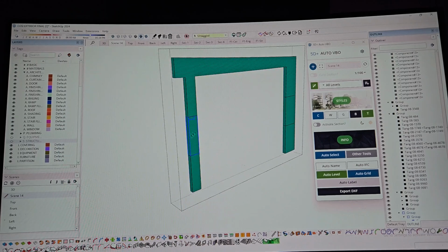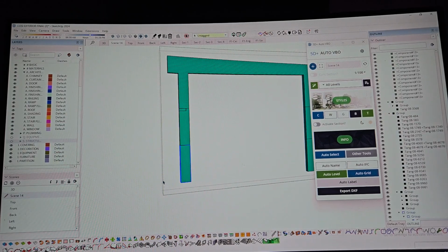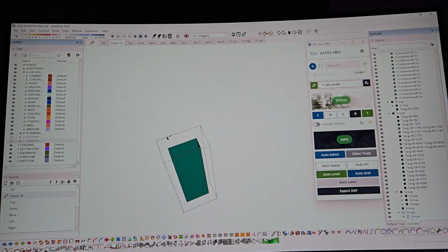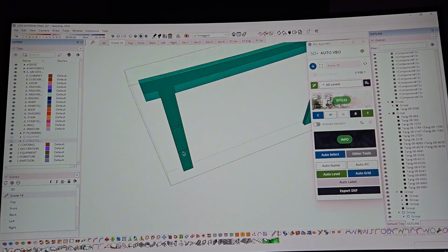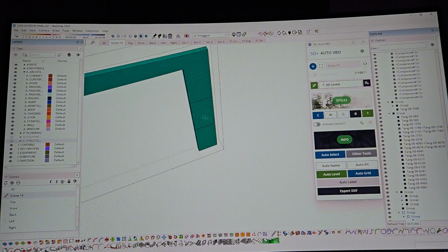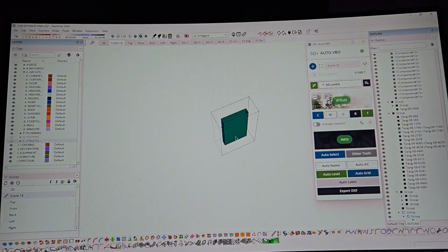So what I'll do here, because it's all in one group, I want to divide them per floor. I could just copy that and make the lines and then group. However, this is where the make face will come in. So that becomes one whole solid if you don't want to make it hollow. See that? Because if you group it, it might be hollow later on.